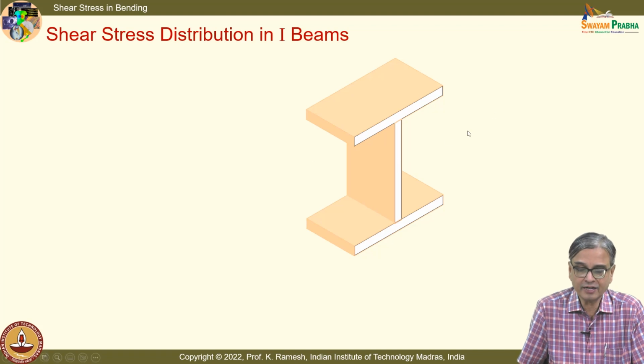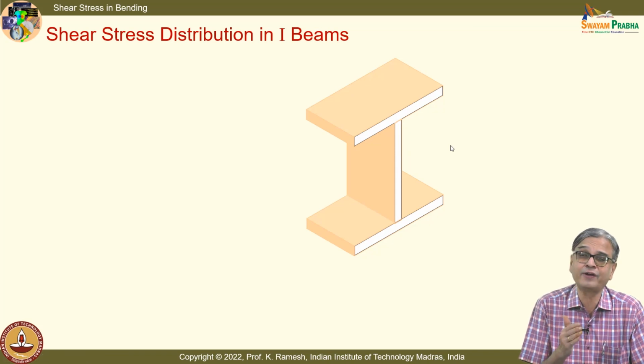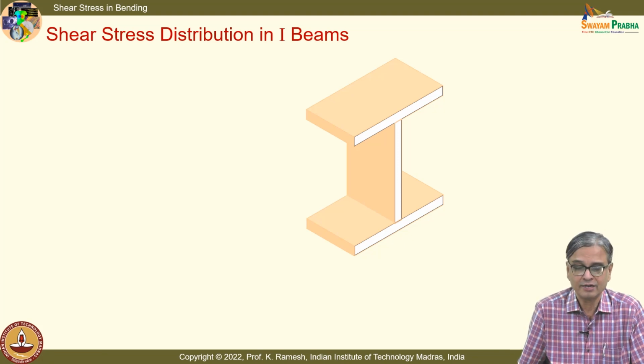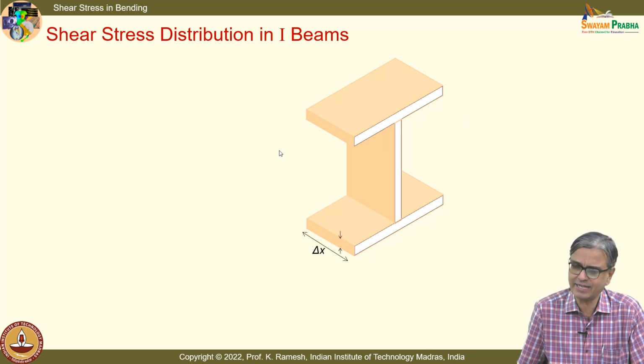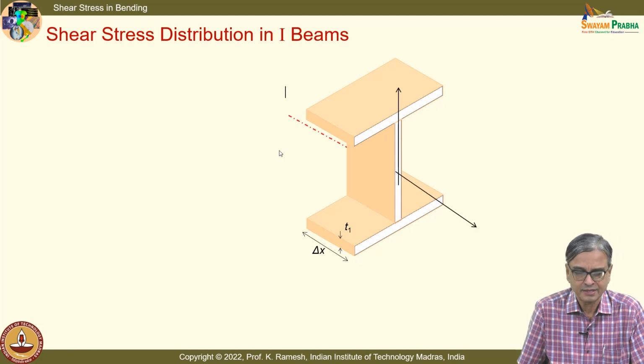See, I will have to make a horizontal cut. I will also have to make a vertical cut. Only then I will be able to find out the shear stresses in all parts of the I-beam. Even before I go and do the calculation, let me show what way I would calculate this Q. The same Q is going to come in some other form. Fine. Let me see whether you look at and you are able to guess what is happening.